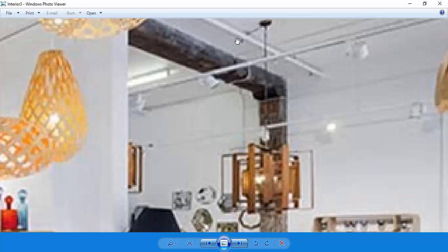Yeah, termites maybe, if they did a lot of damage over time. So with a timber building like this, if you have exposed timber structures, it's harder to get a fire rating for that, and you won't usually get a fire rating that's high enough for the type of building. So what often you need to do is build a new floor above the existing floor. That way you can have the bottom exposed and still see the nice timber floorboards from the bottom.